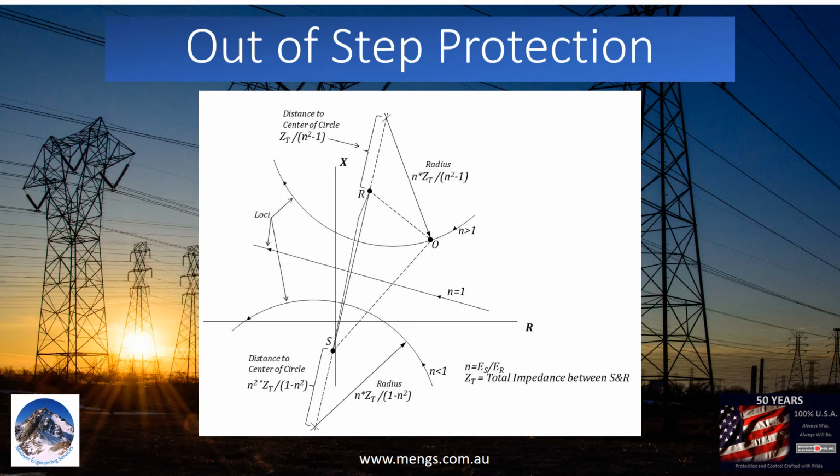Measuring variations in system impedance helps to detect an out-of-step condition and define the schemes for out-of-step protection. Settings applied to these schemes are critical to system reliability and stability. The schemes must be set to quickly isolate a machine, not only to prevent damage, but also to prevent instability from spreading to other portions of the system.